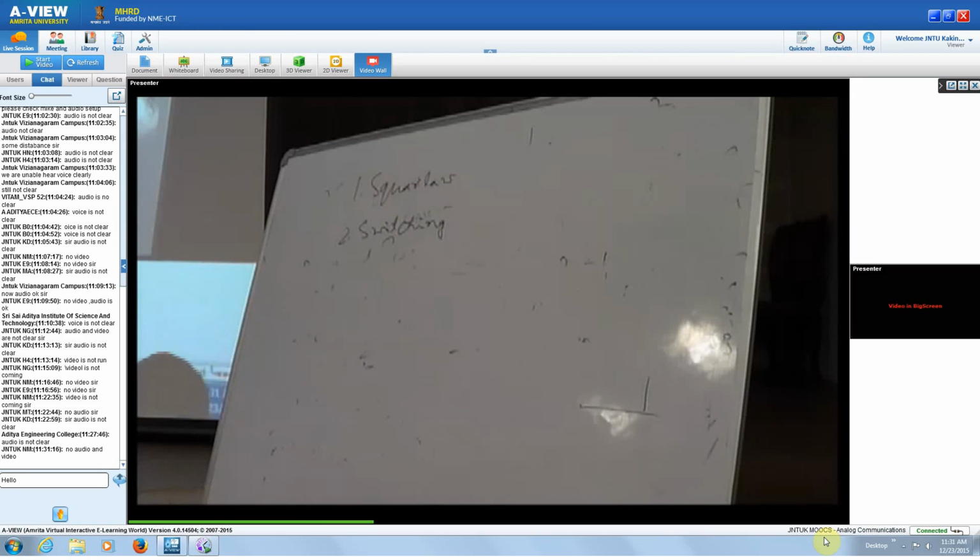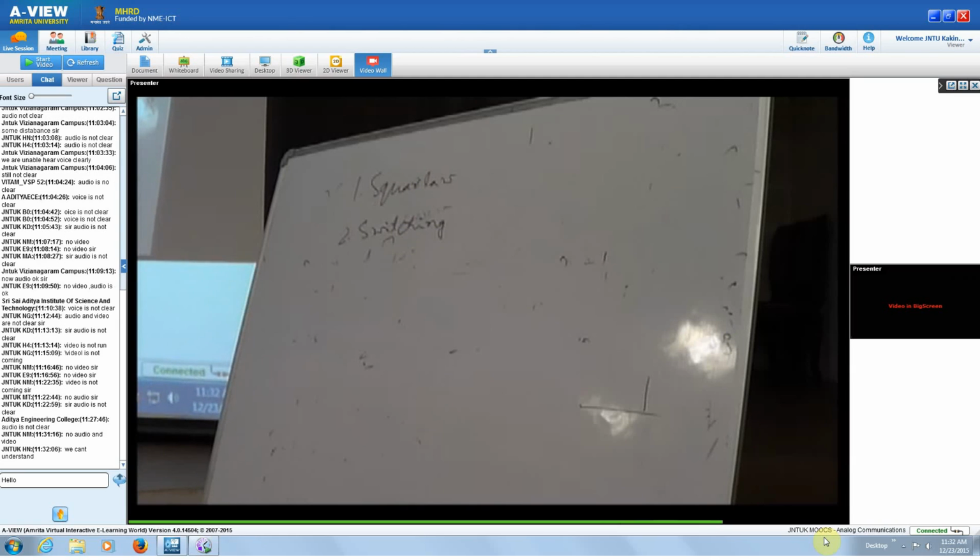So this will have a combination of these two signals, the carrier signal and the baseband or modulating signal. So we have a circuit to combine these two. Then we are going to have a nonlinear element, as we are saying the square law. So we require a nonlinear element. What is the nonlinear device that we can have?